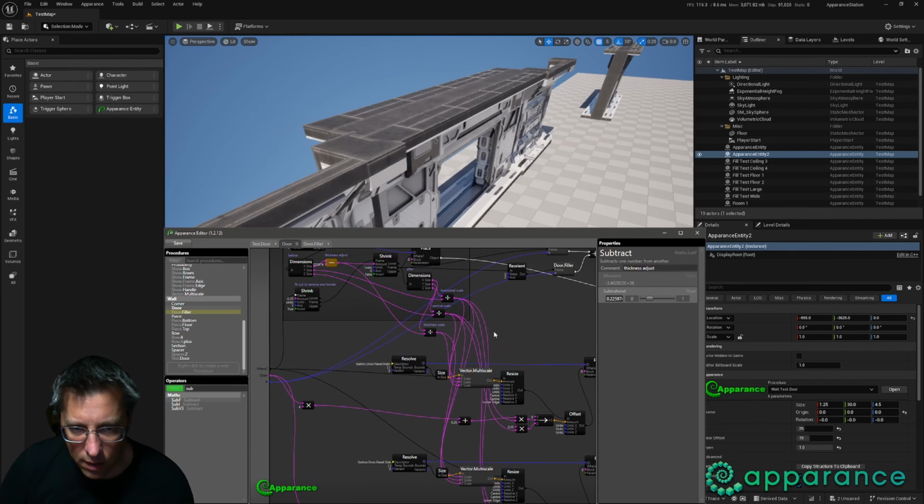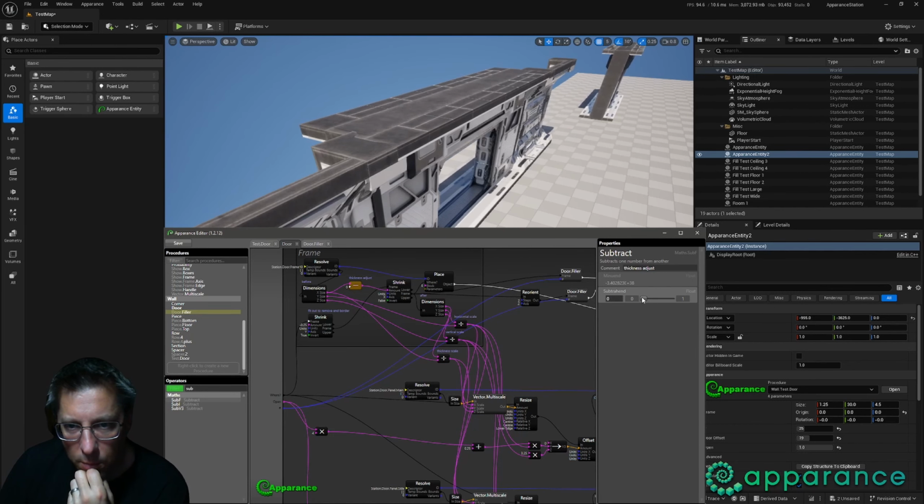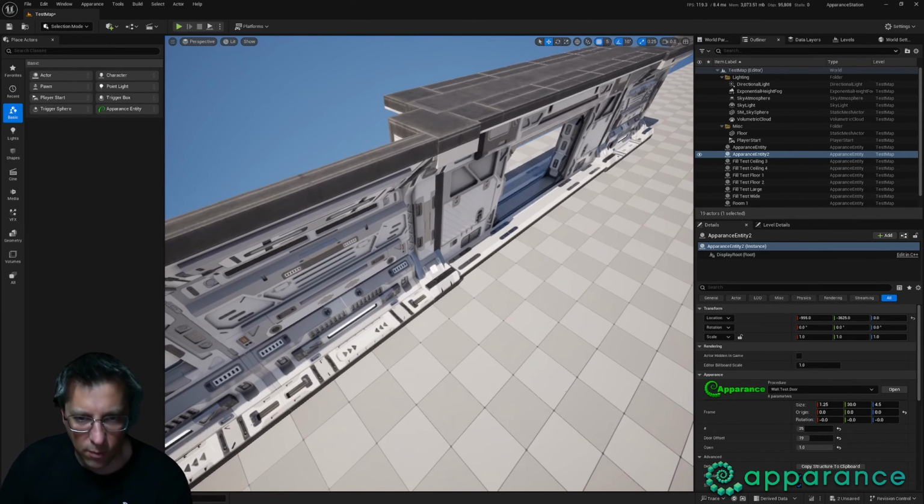Thickness scale X after. Oh no, that is the right. The before is before this adjustment, and because this is the value passed in here, the after. Yes, that's better. So if we change this, we can see the wall panels shrinking as well. That's good. So we need to work out what a good size is to hide all our mischief.